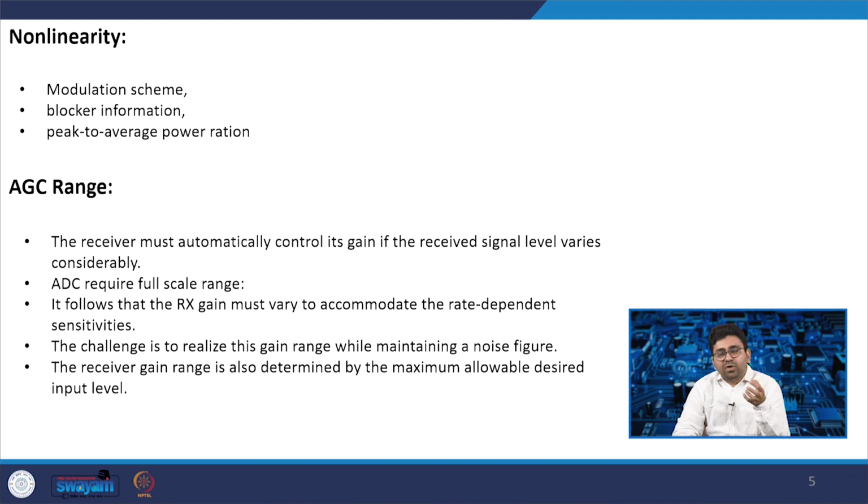We already discussed in the oscillator, while discussing oscillator phase noise, that based on the interferer and the blocker level, you can also estimate the phase noise of your oscillator. So various parameters you need to list out for each component that you are going to design and put into the design criteria.